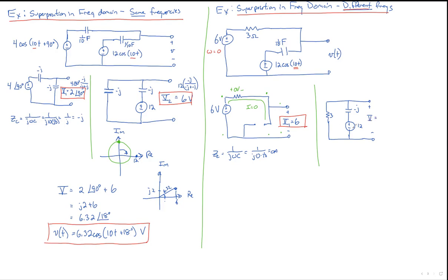We've got a 12-volt source, 2 impedances in series, and we want to find the voltage across this 3. So by the voltage divider rule, it's equal to the one we want to find it across, the 3, divided by the sum. And throw that in the calculator, and we get 11.4 at an angle of 18 degrees. That's our second partial.